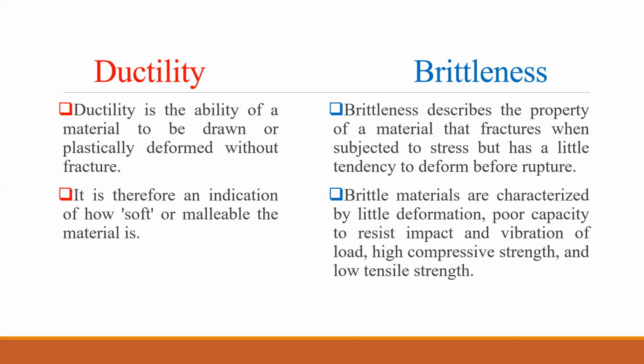Whereas the brittle material will not undergo plastic deformation. Brittleness describes the property of a material that fractures when subjected to stress but has little tendency to deform before rupture. Brittle materials are characterized by little deformation, poor capacity to resist impact and vibration of load, and brittle material has high compressive strength and low tensile strength.